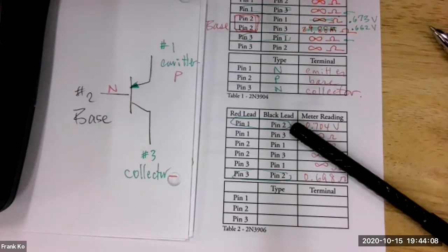Is a rectifier a type of transistor? No, a rectifier is a diode. The PN junction device is the two-layer device. Your transistors are three-layer devices. So we have different kinds of three-layer devices. The BJT is the most basic three-layer device. There are also four-layer devices. Your thyristors, your SCRs, silicon controlled rectifiers, are four-layer devices. So diodes are two-layer devices. Your LEDs are two layers. Rectifier diodes are two layers. Anything that's a diode is a two-layer device. Transistors are typically going to be three layers.